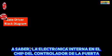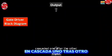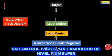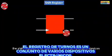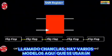Now, we are going to tackle the heart of the matter, namely the internal electronics in a gate driver chip. This chip contains a succession of electronic functions cascaded one after the other. Thus we find a shift register, a logic control, a level shifter, and a buffer. The shift register is an assembly of several electronic devices called a flip-flop. There are several models. Here will be used the flip-flop D.